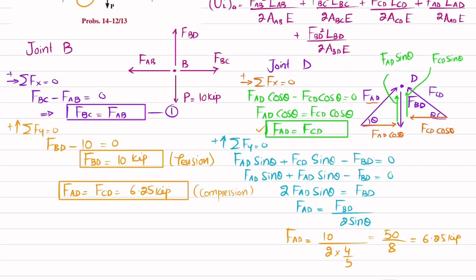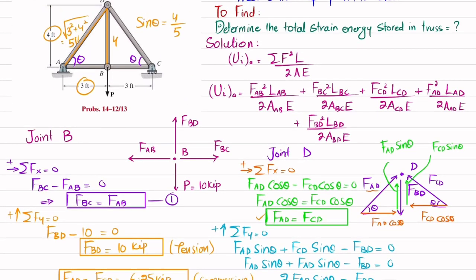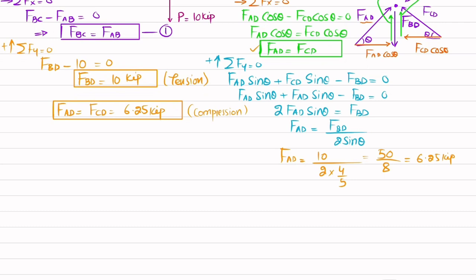Okay. Now we will apply method of joint at joint C. So you can see here you will be having one load that will be the reaction force, which will be Cy, and this will apply load in this direction, and this member will apply load in this direction. Because you can see due to this load, this will be in tension. As a result, this will exert force at point C in this direction, and this member will exert load in this direction. Clear? So we will draw the free body diagram at joint C.